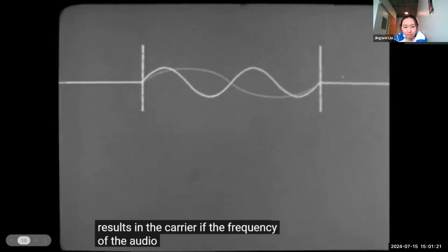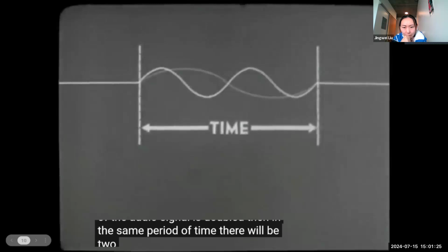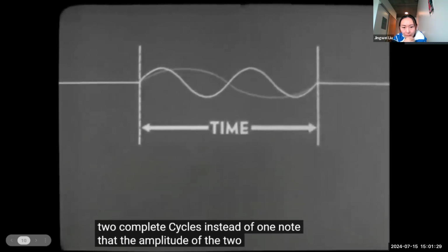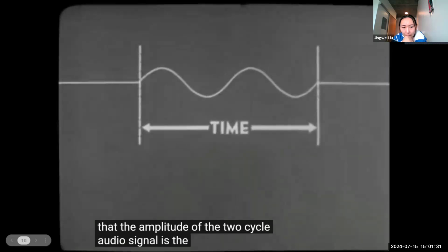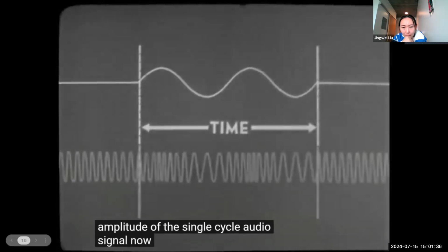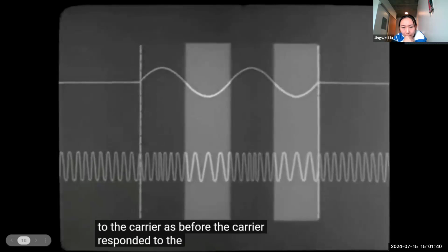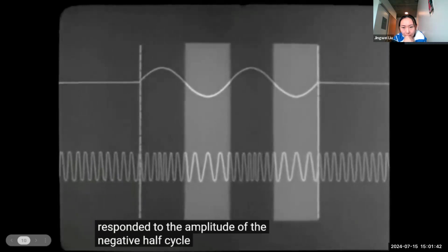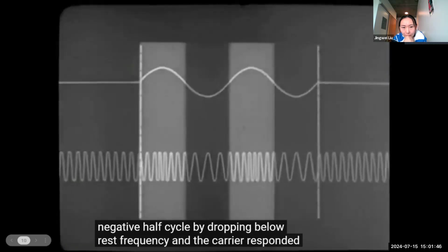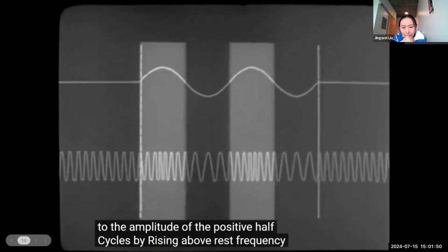If the frequency of the audio signal is doubled, then in the same period of time, there will be 2 complete cycles instead of 1. Note that the amplitude of the 2-cycle audio signal is the same as the amplitude of the single-cycle audio signal. Now let's see what this has done to the carrier. As before, the carrier responded to the amplitude of the negative half cycle by dropping below rest frequency, and the carrier responded to the amplitude of the positive half cycles by rising above rest frequency.